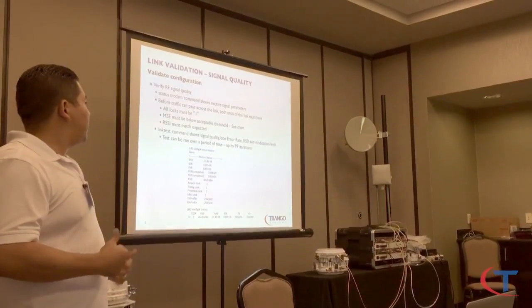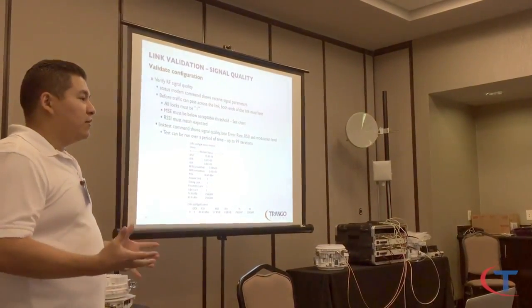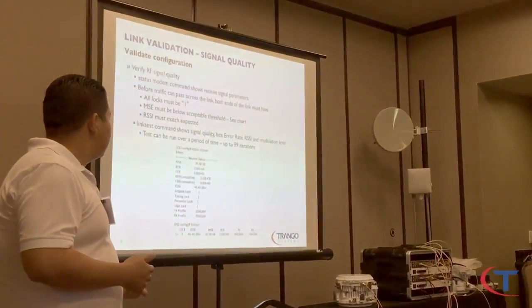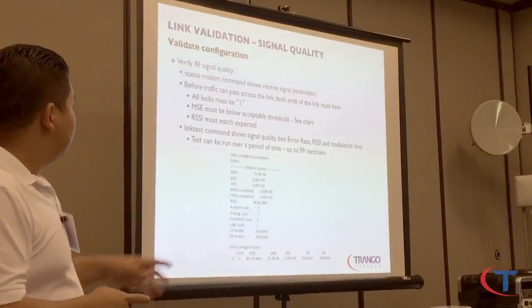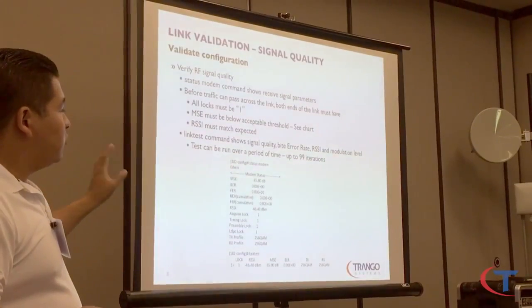First of all, we're going to verify the RF signal quality. How do we do that? We're going to do a link test. All must be ones. All the links should be ones. The MSE must be within an acceptable threshold.